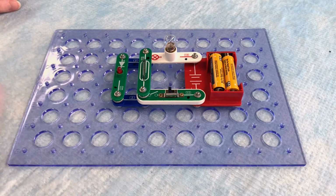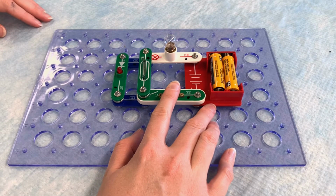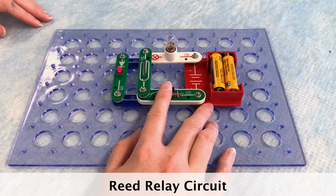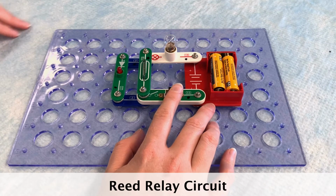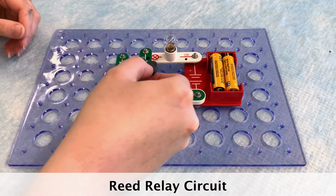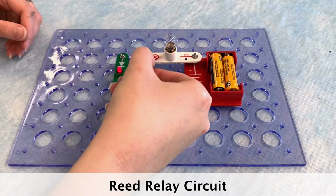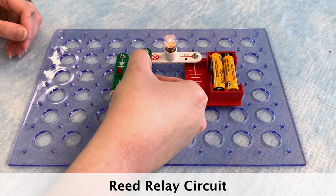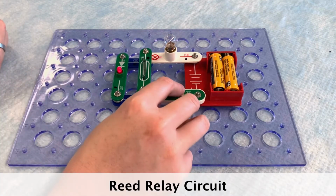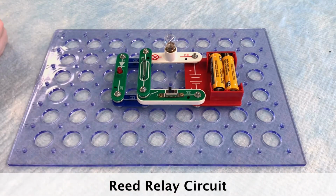The reed relay circuit, which I have assembled here, is a switch device controlled by a magnetic field. When you flip the switch, only the LED turns on because there is not enough power for the bulb. When moving the magnet close to the reed relay, the two reeds inside connect and close the circuit. The LED will then turn off and the bulb turns on. This is because the electric current takes a shortcut through the low resistance reed relay circuit.